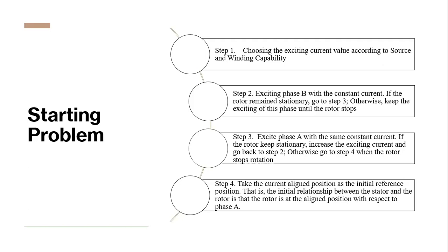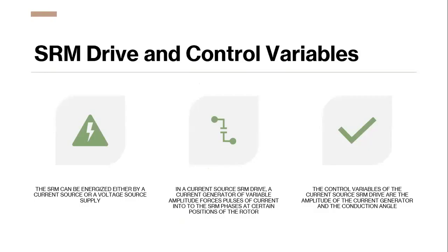After the excitation, we have to go to the next phase and excite the next phase according to the rotor positions. We have to calculate the current, otherwise it will still not be excited. We have to determine the flux linkage model and the resistance of the winding for connection of these windings. Okay.